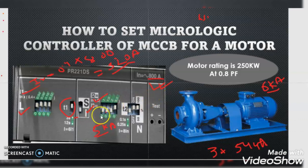But as per your wrong setting, the circuit breaker is capable of taking only up to 5 kilo ampere. Then what will happen? This circuit breaker will fail to operate, as the prospective fault current at the motor level is 6 kilo ampere. So the circuit breaker will fail to operate, and finally the motor will burn out.